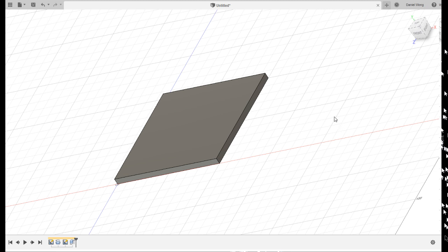The first thing I'm going to do is, because when you're playing some serious mahjong you're going to be resting your wrists on the edge of the table, we're going to need some fillets to make a nice smooth rest for them. So I'm going to go to modify, fillet, and we're going to fillet the top edges of this face here, so I can left click each independent edge, like so.